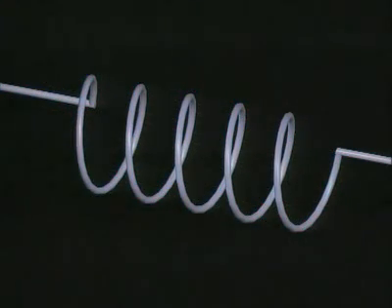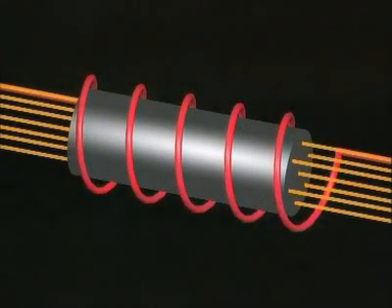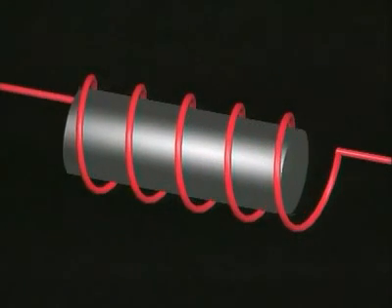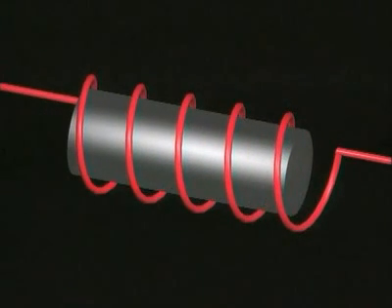If a soft iron core is inserted into this air core coil, the electromagnetic force is amplified considerably. This is the principle on which solenoids are based. Another phenomenon. If the soft iron core is movable, it is drawn into the middle of the coil when current is applied, thus producing a magnetic field. In this way, the core has the function of an armature. We will take a close look at this specific effect in the section on solenoid valves.